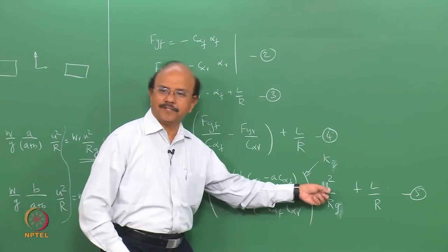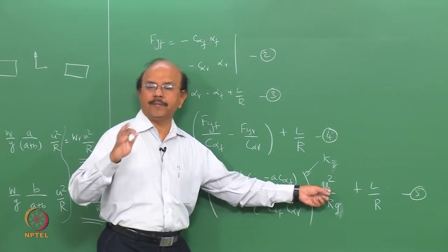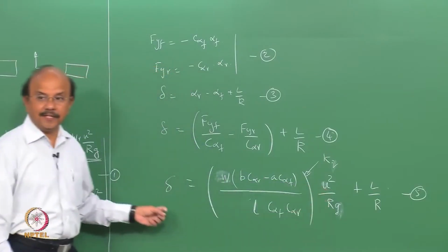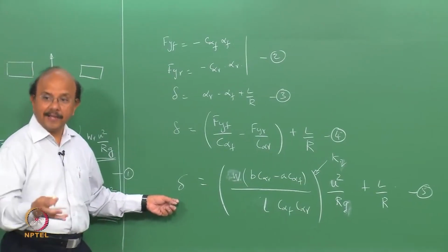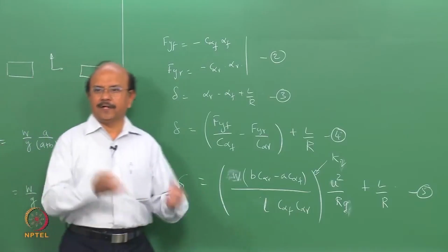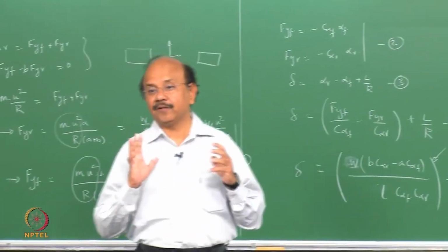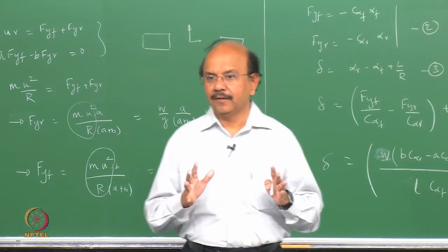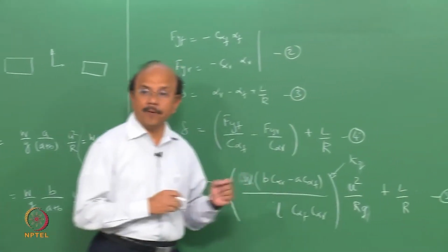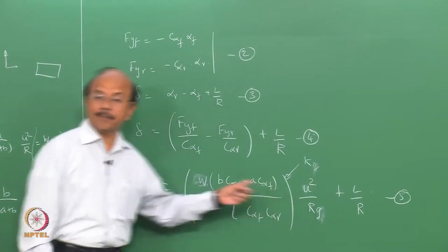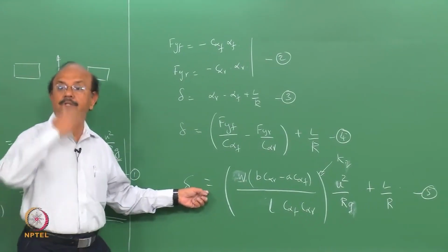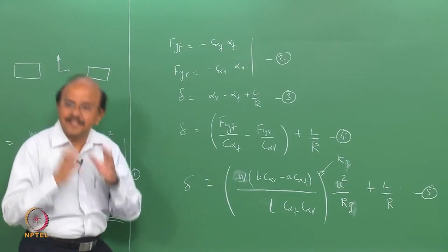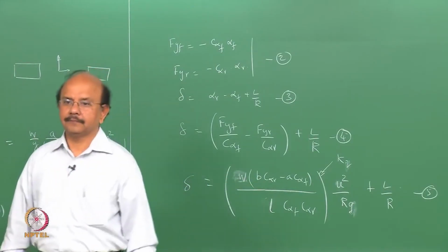So when he presses his accelerator, in other words, which I shouldn't say because we are looking at steady state, when the velocities are high, his steering input has to be higher. In other words, if you take a turn at 40 kilometers per hour or take a turn at 80 kilometers per hour, your delta is different, which is a factor that is very important to understand. Note that when you increase the speed, delta increases. That means that much more steering input you have to give. So that is something you also have to consider when you look at understeer gradient. Clear?